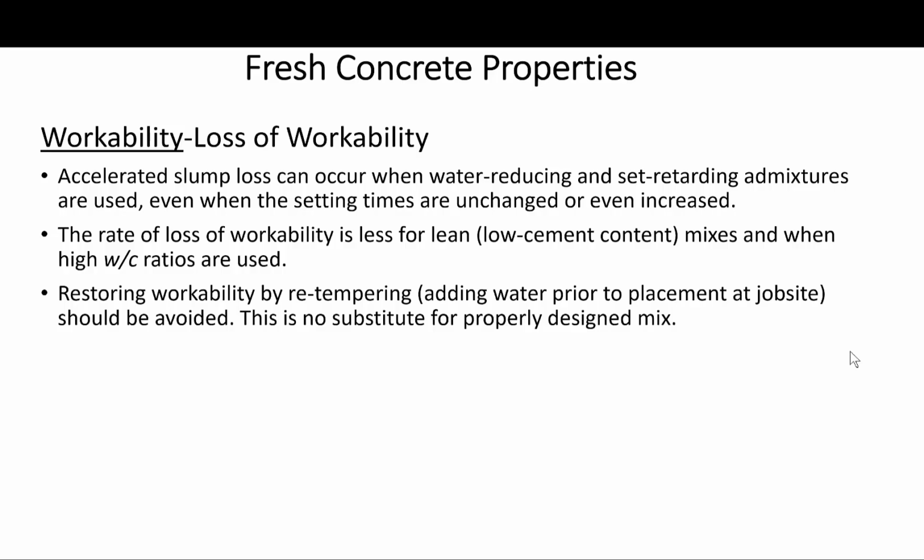So I am going back to emphasize something I have said when talking about workability and other fresh properties. Consistency and uniformity are important. Also, if the concrete mix is improperly designed, it may be necessary to remix the concrete with additional water, what's referred to as retempering, just prior to placement in order to restore workability.